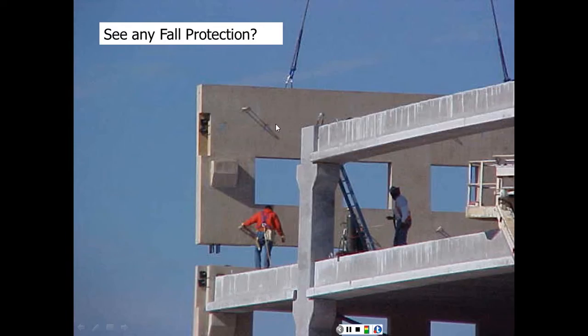Here we have precast concrete. It seems we have here, I'm not exactly sure whether this is a PFAS or not. It seems we have one, but it doesn't seem to be properly tied to any anchor points. And here we have a ladder. It doesn't seem to be extending 3 feet above the landing surface, if there's going to be a landing surface here. So there might be some issues in this picture.